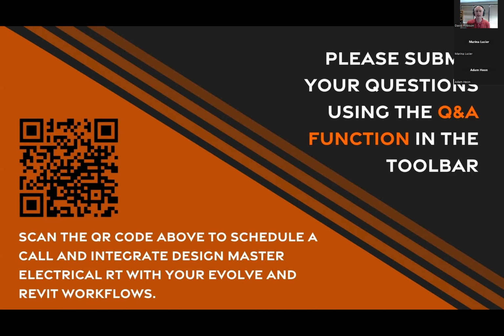However, a lot of times, you're starting with your one line. You don't even have a Revit model. You don't have your equipment yet. That's kind of the standard workflow. The first thing you do is you create your one line. In that case, you can actually create your devices directly on the one line here. So I can create panel P new. It's going to be a 480 volt panel.